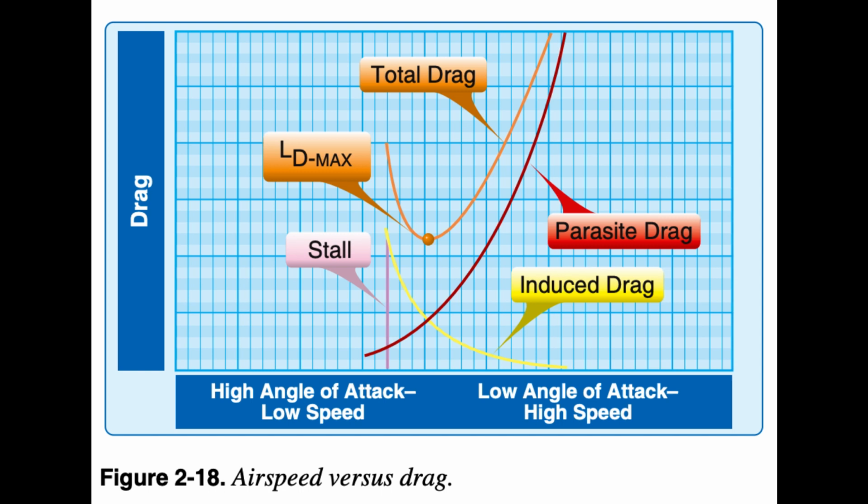It is high at the slowest airspeeds at high angles of attack near the stall, decreases to the lowest at the most efficient airspeed, and then progressively increases as the speed increases. The WSC wing can fly with a large range of airspeeds. Generally, the most efficient speed is at the lowest total drag, providing the best rate of climb, glide ratio, and cruise economy. However, slower speeds provide higher angles of climb, and faster speeds provide quicker transportation.